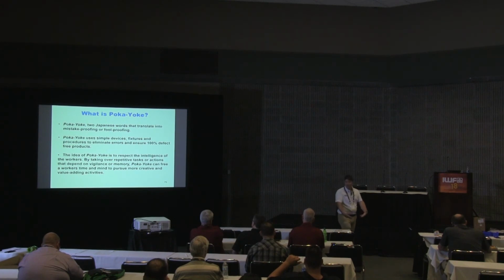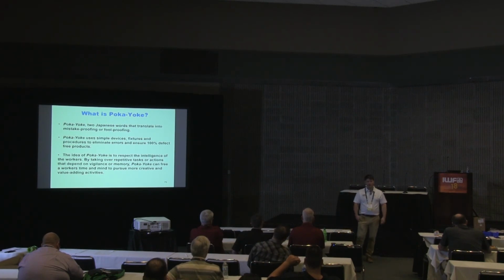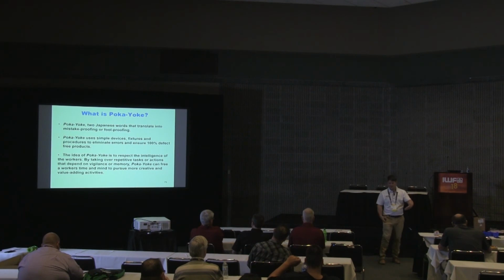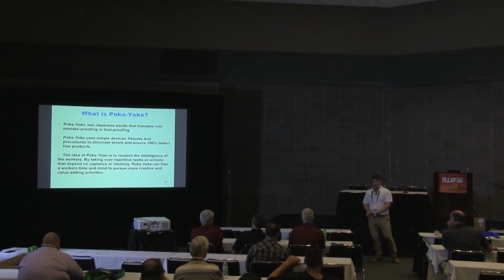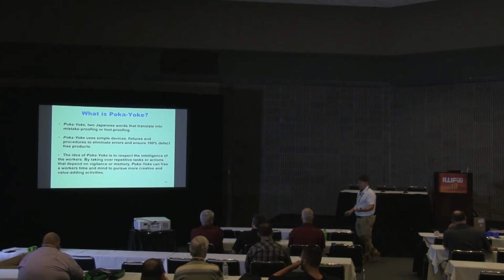Because when you have something on a workbench and you see it a million times, you very easily put a sticker upside down. And then you go to put it on and it goes, how could you put that upside down? How could you be so stupid? Well, I've seen a million of these. They all look the same after 50 million. It's like, okay, how do you fix that? Put a little notch in the label, right? Mistake goes away. QA defects, no rework.